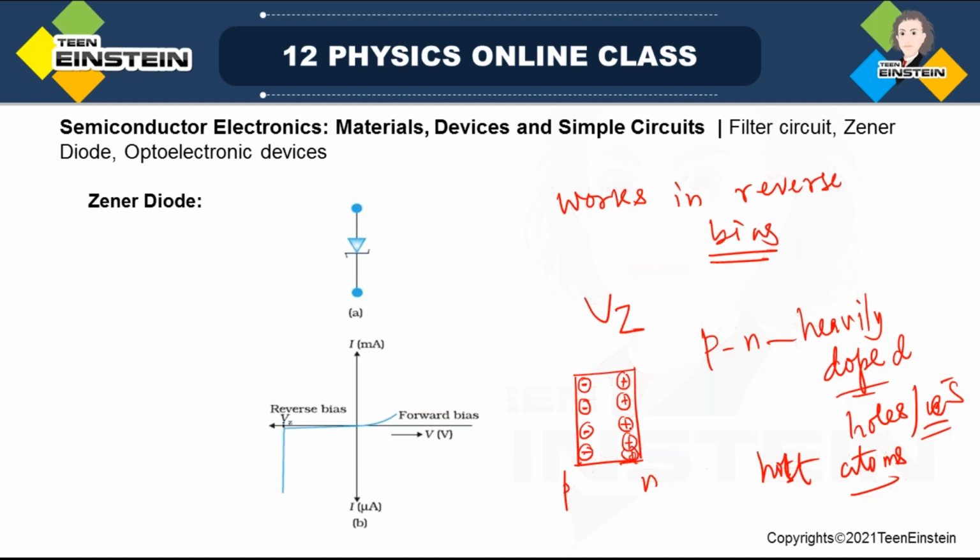Okay, sitting over here, now already there is a built-in potential that is called barrier potential. Okay, we had written that time. This is V_i, or you can write simply V0. This is a barrier potential. Sometimes it is written as V_B also. Let me write it as barrier potential, or built-in potential, that is V_B across the junction because of this depletion layer.